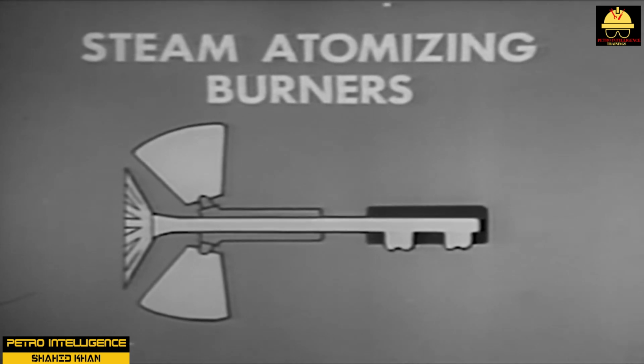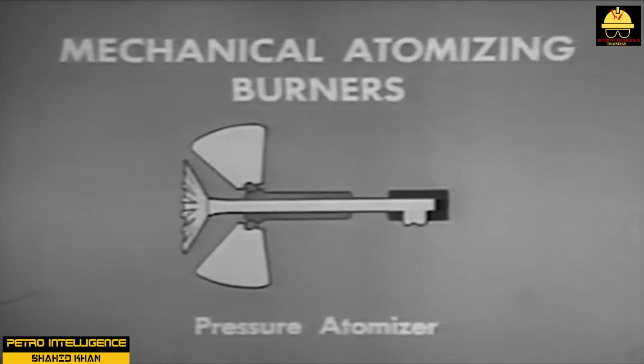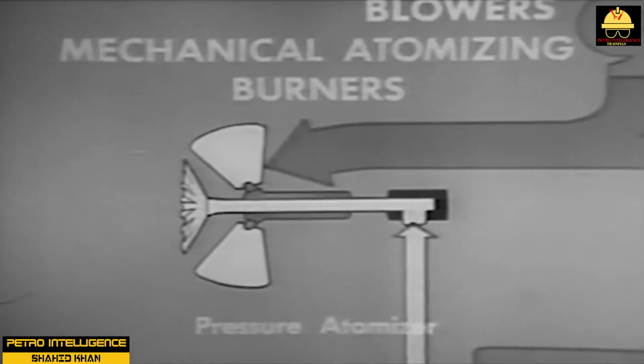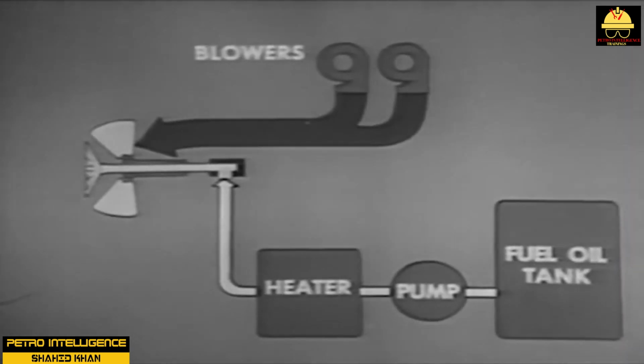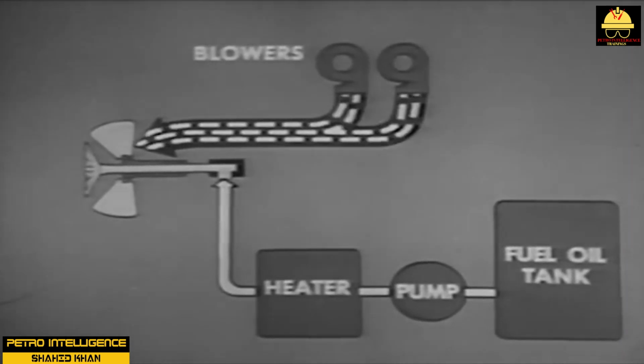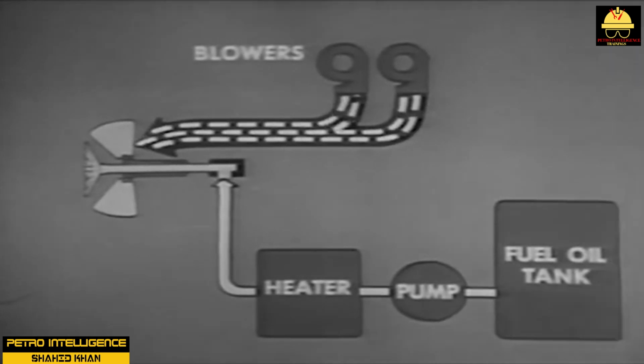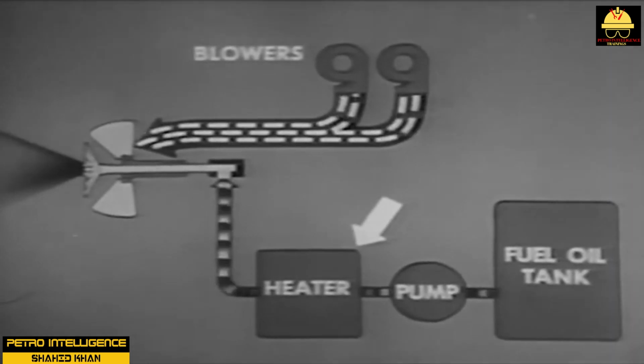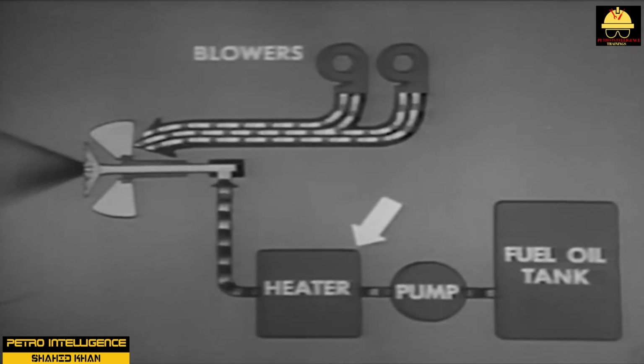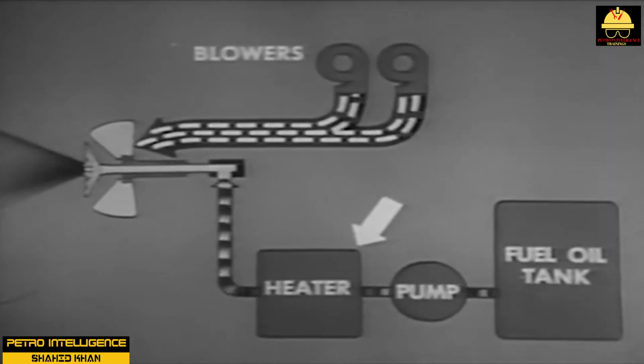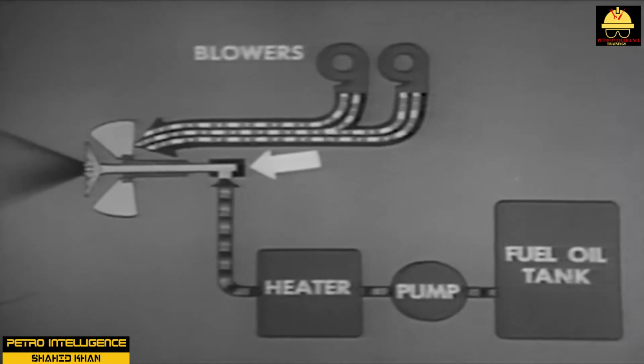Pre-mix burners pull in primary air for combustion through a Venturi-type air-fuel mixing device. They respond to changes in firing to keep the air-to-gas ratio relatively constant. Secondary air registers are provided in pre-mix burners. Burner alarms are located on each burner and will immediately alert a technician when a burner goes out or is functioning outside normal parameters.